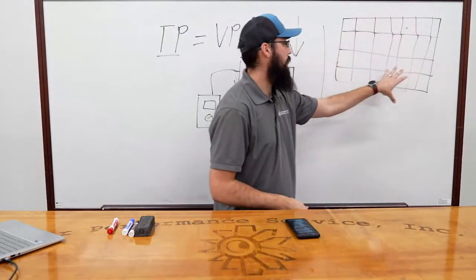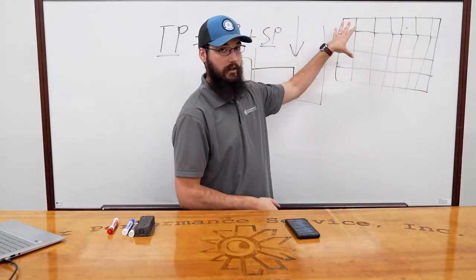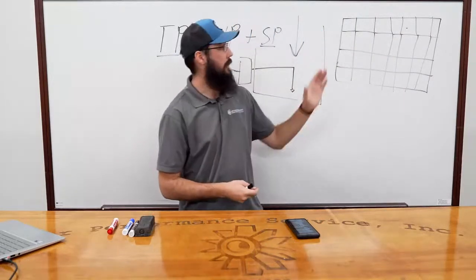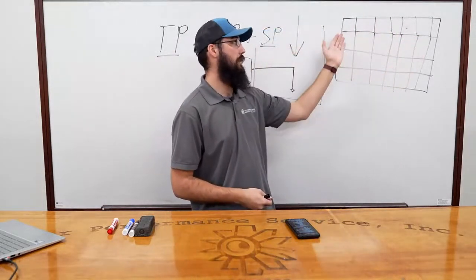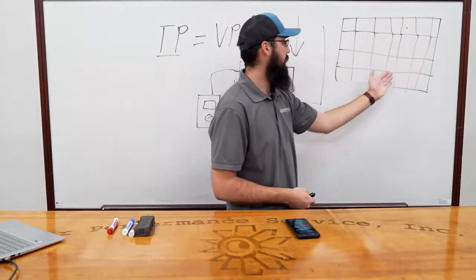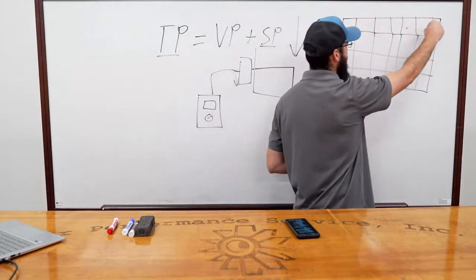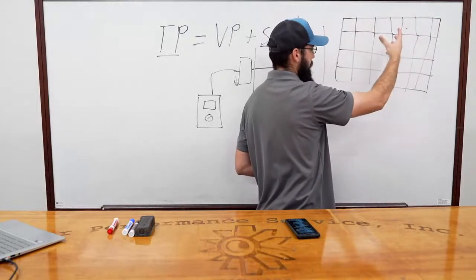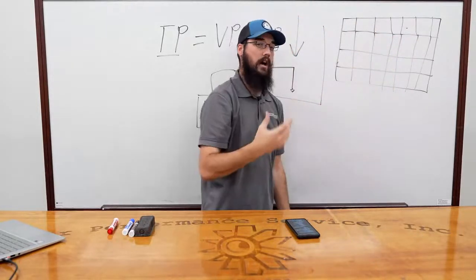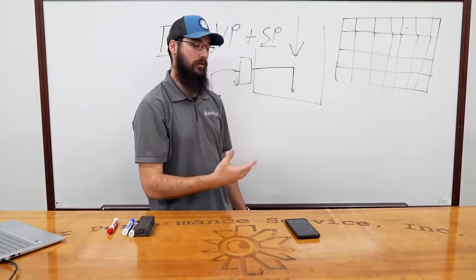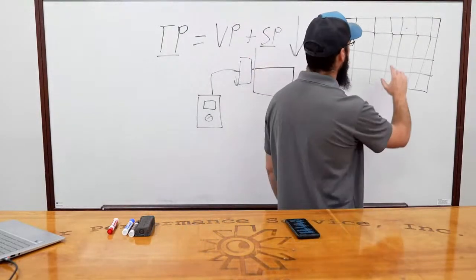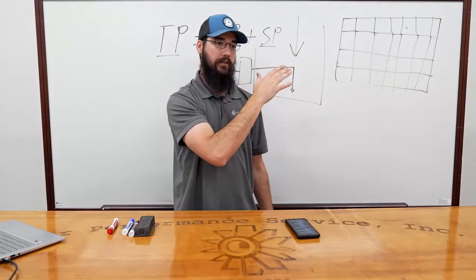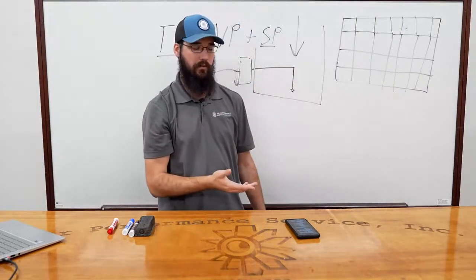And so you end up having to do an area calculation, and that area calculation is built into your FPM, and that FPM is going to change. So what you're looking for is the average. You have to take FPM all the way across, because the FPM on the edges is going to be lower than in the middle. You have to average it, because if you just take it in the middle, you'll end up getting a higher reading than you're actually moving, and so it's not as accurate. So that's what you have to be careful with. Anyway, this is a more in-depth method that is something to have in the toolbox, not something to use very often.